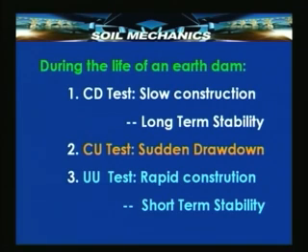We saw in particular the application of the different types of drained and undrained tests with a typical example of the earth dam. During the course of the life of an earth dam, there are several stages it passes through, starting from construction to reservoir filling and drawdown to long term stability. And under each condition, the shear parameters which apply, which must be used in order to test the safety of the earth dam, will vary, and the type of test that will give the appropriate parameters will also vary.